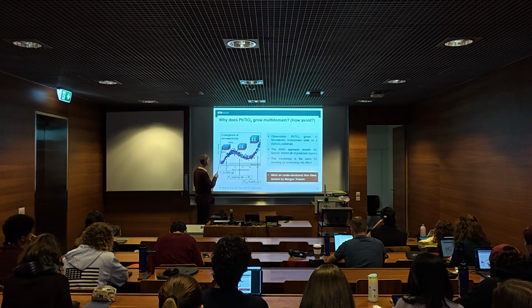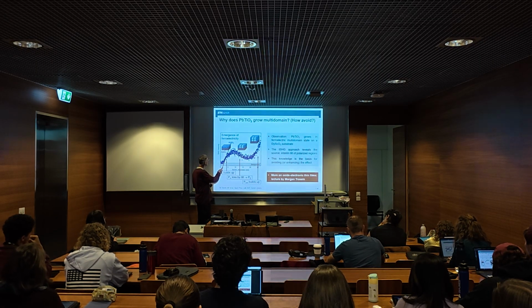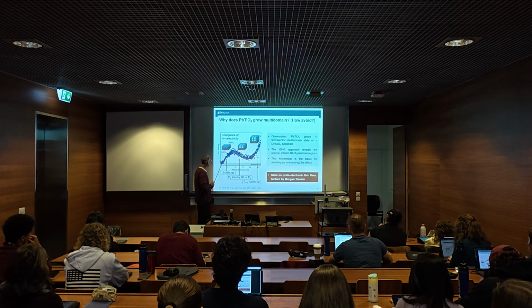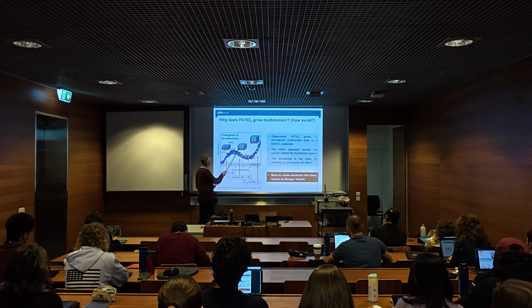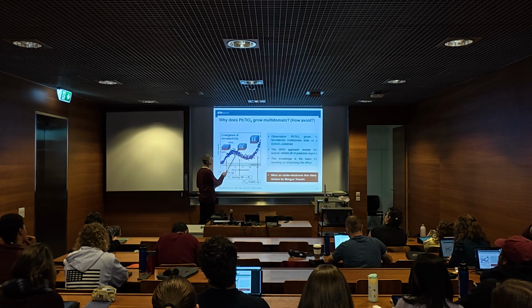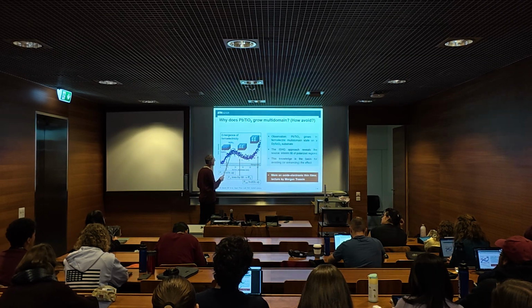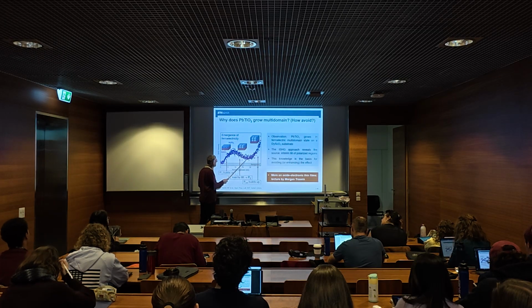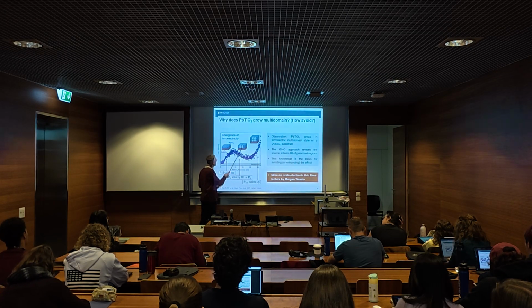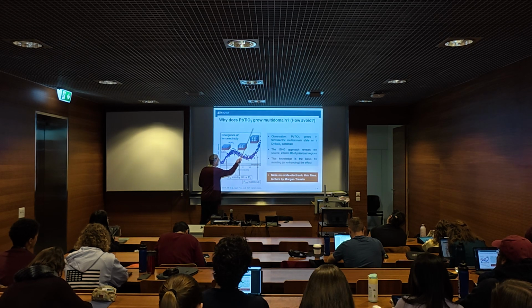And what that tells you is you grow that titanate with an out-of-plane polarization, and that makes this signal. At some point, the polarization flips into the plane. So you lose contribution to your out-of-plane polarized signal, you really lose it, so it goes away. Until this multi-domain situation stabilizes, and then the entire thing grows in thickness again.